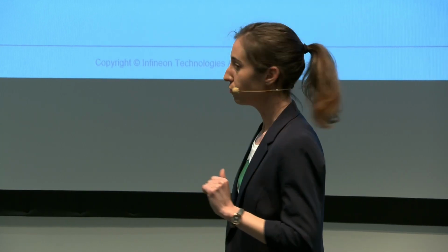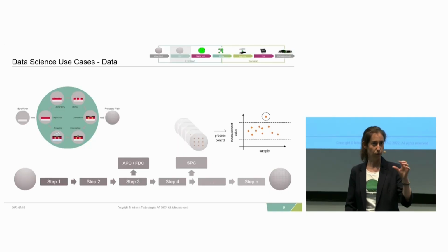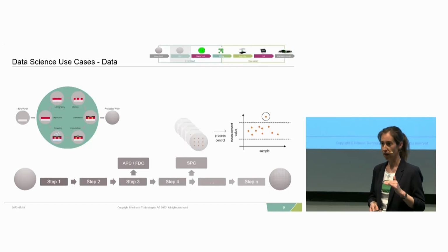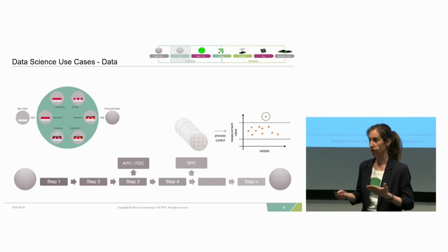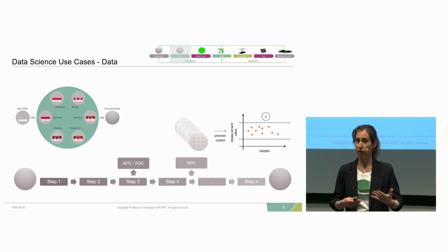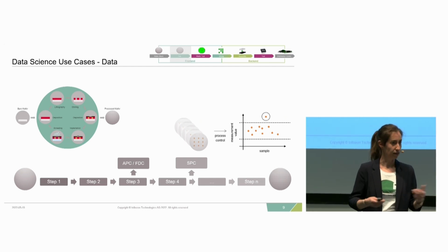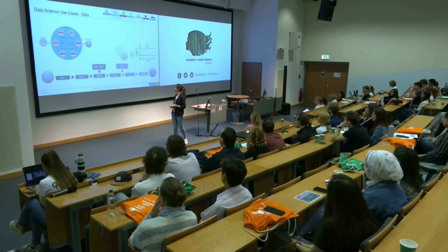And same for statistical process control. You take samples out of the production line to check whether, for instance, the thickness of your wafer is still within predefined limits or not. Here we are just dealing with sample data, because we cannot always measure everything, and this is also not needed, because we have methods in place which can provide good predictions and provide insight into the whole area.